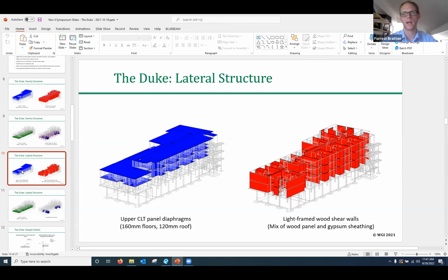But in any case, they wanted us to locate as many penetrations as possible so they could pre-cut them, because it can be difficult to cut the cores in the field. And so we had essentially a CAD document that was discussed and shared to try to coordinate those ahead of time. But for various reasons, that process was compressed, and in hindsight, maybe a little faster than it ought to have been. Some of those plumbing penetrations didn't end up in the right place, and so then it became a field issue. How do you cut through a panel where the plumbing penetration is 7 inches or 5 inches away from where it needs to be?